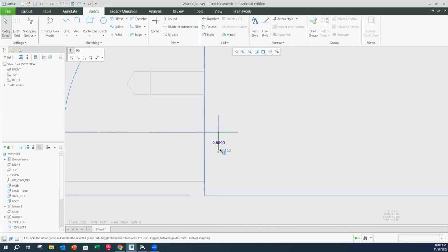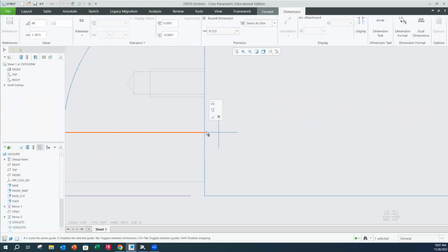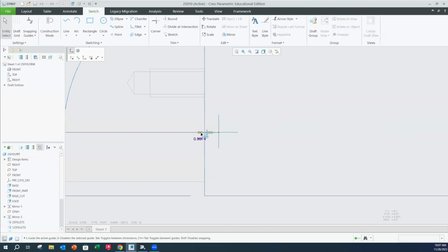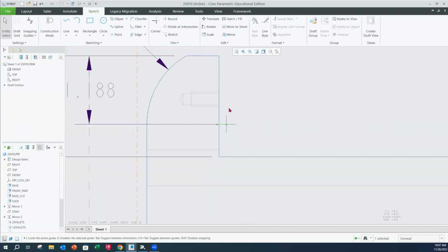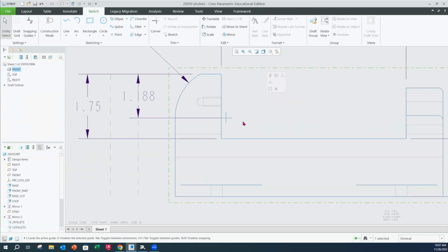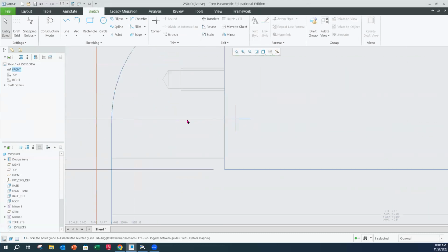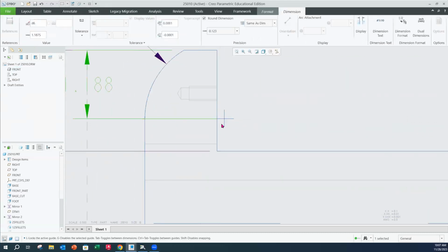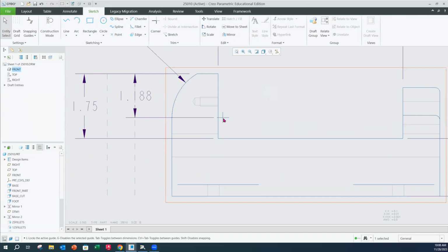Now remember, we're in a drawing, so it's not intended to be like this fantastic sketcher. It's really not its intent, but that's okay. So now I've got that in place, and that's just a little crosshairs so that when I select this dimension, I can grab this and pull it away so that I see the gap to what would be the center for that radius.